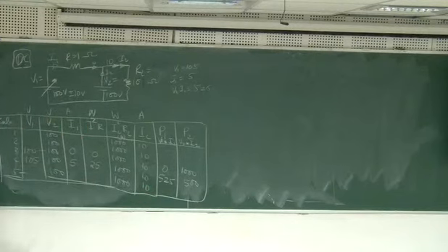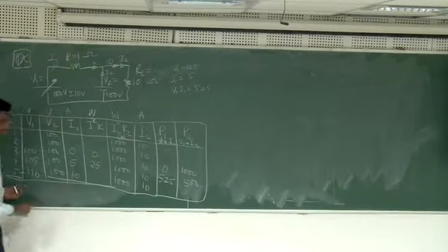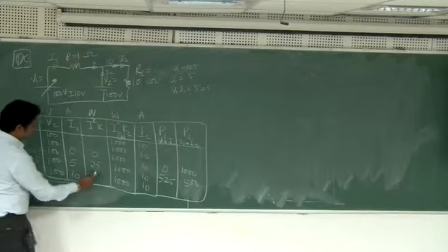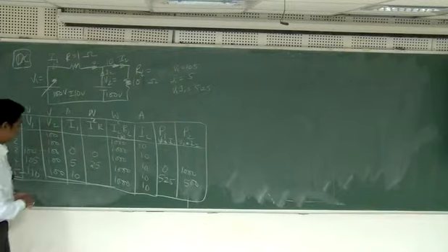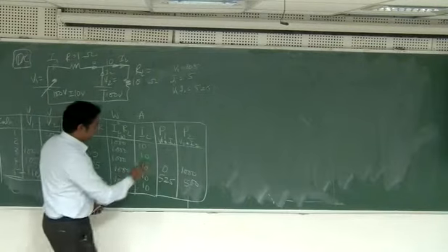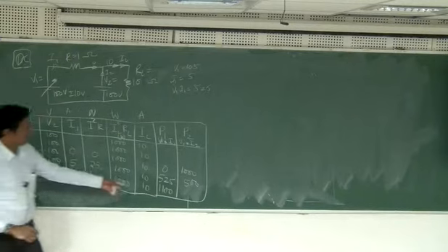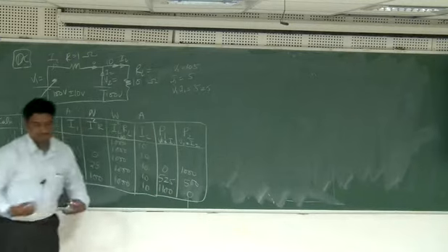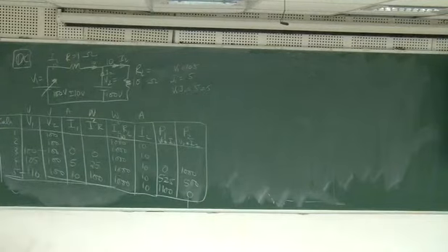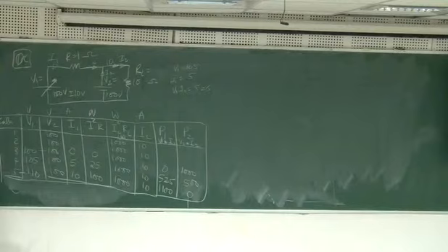Okay. So you are slowly starting to understand some point here. Now 110. If I use 110, the entire 10 amperes comes from here, and what will be the I square R losses? 100 watts is lost here, because 10 square into 1, and V1 I1 will be 1100. And then this one will be 0. There is no power sharing on the second one. So you are arranging the voltage in such a way that by the time the current reaches here, the whole current is supplied from this side only, and I2 will not be there.